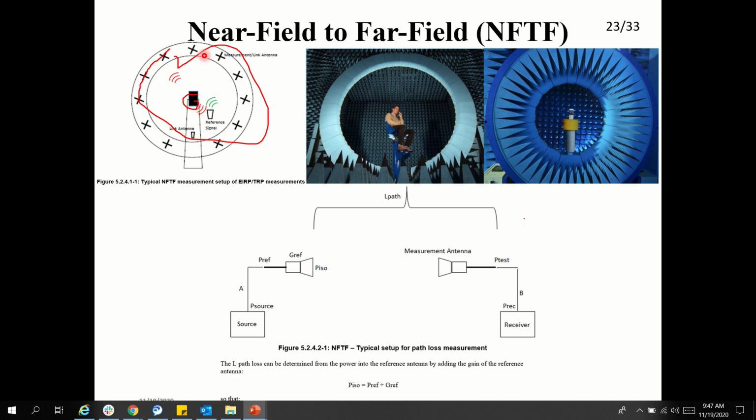Then we will capture all that information. In some near field measurements, we place a probe very near to the device in order to see whether a signal integrity problem is there or not, like mutual coupling between two components in the circuit. If you have a very big structure, then you cannot move it often, so that's why they go for near field measurements. There you can find signal integrity problems, EMC problems, and radiation problems.